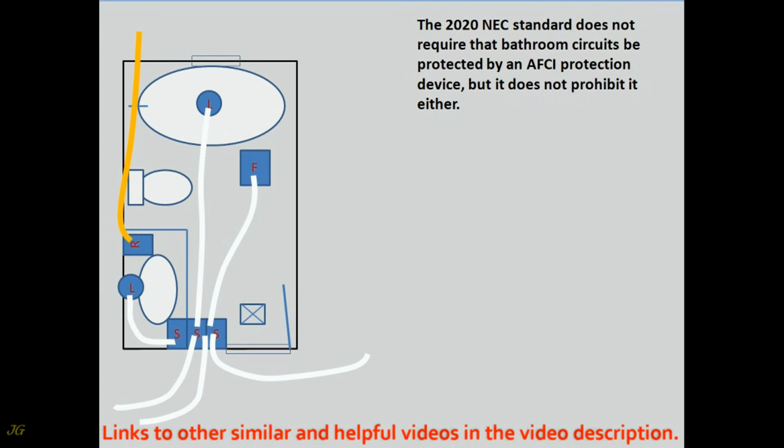The 2020 NEC standard does not require that bathroom circuits be protected by an AFCI protection device, but it does not prohibit it either.